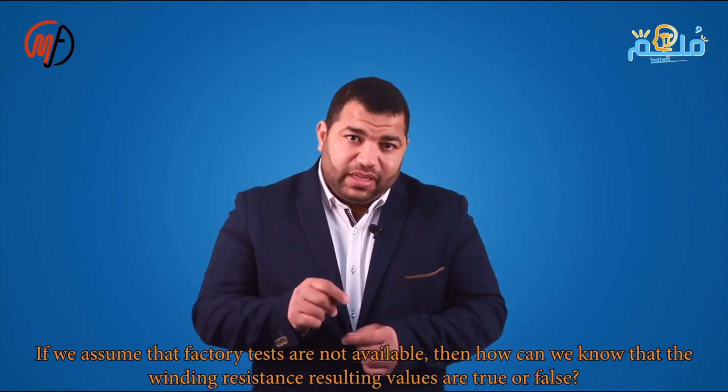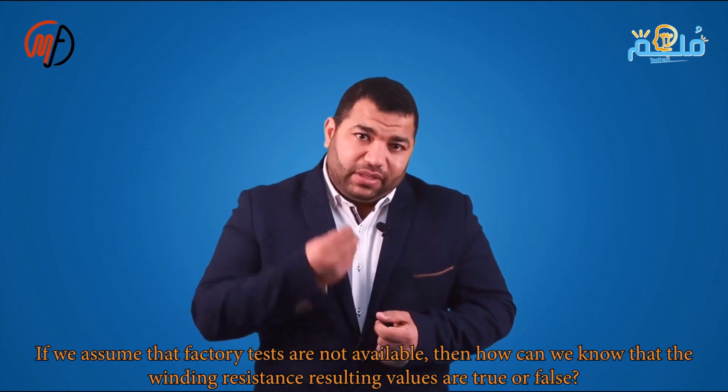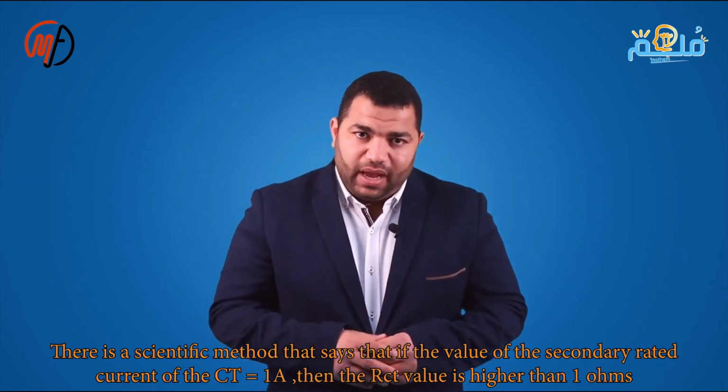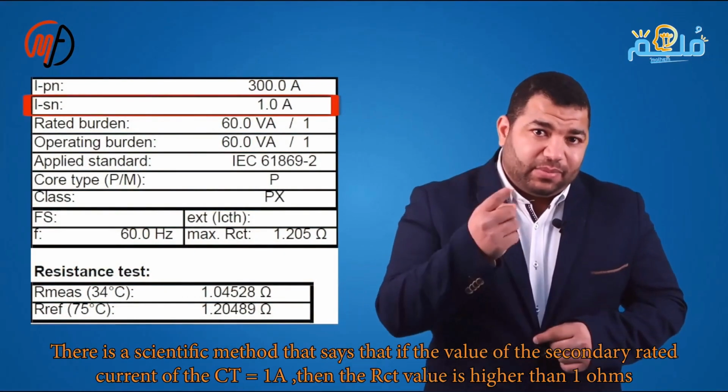Let's assume the factory test report is unavailable. How to ensure the winding resistance value is correct or incorrect? There's a scientific method stating, if the secondary rated current is 1 amp, the winding resistance value must exceed 1 ohm. However, if the secondary rated current is 5 amp, the allowed winding resistance value must be under 1 ohm.